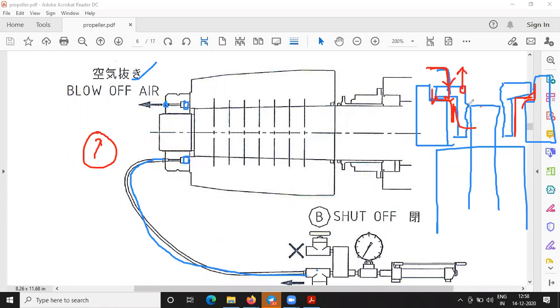Since it is threaded onto the stud, the stud also starts being pulled up, and that is the point you can observe a deflection in the pressure gauge, because that pressure is utilized against the tensile stress of this bolt, and the stud or bolt, whatever it is, starts getting elongated.